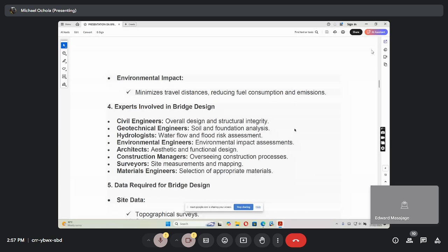Material properties, and if you are modeling and you're designing, that's the first. After your model, the next thing you must specify is the material. So for bridges, the material grade seems to be on the higher side because of their exposure condition. They are exposed. A building is exposed to mild conditions, but bridges move from severe to extreme. So that will also guide you.